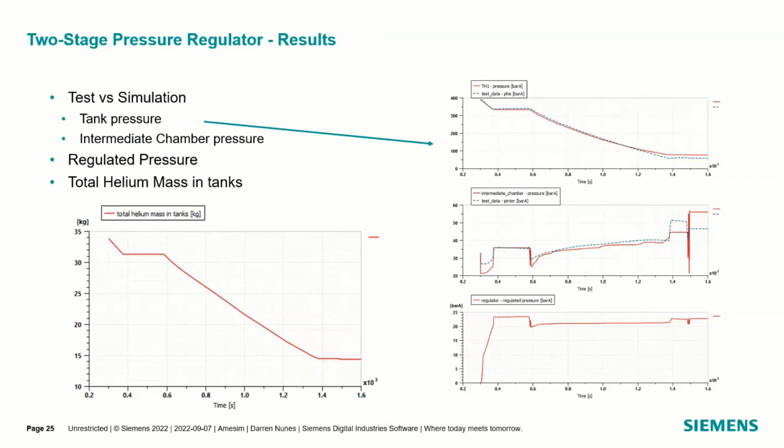The pressure at the end of the thrust phase we can obviously improve based on that intermediate chamber. We maybe could have overestimated it or changed some of the parameter sets to have it ideally match as well. But the great thing here is you can see that even through the decreasing of that helium mass, at the end of the thrust phase we still have 14 kilograms available. That's not enough for the passivation stage. So to clean up the system, we could maybe eject the surplus of fuel, or design a better propulsion analysis there, or change our parameters of the tanks.